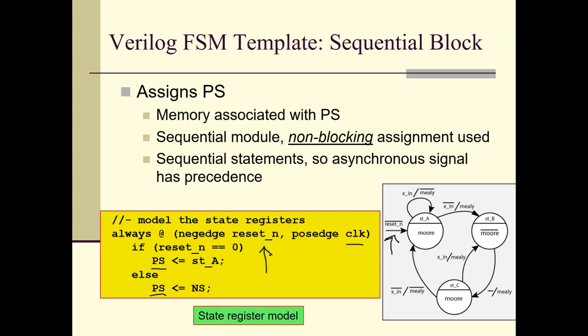This is done a little bit differently, and you can see it in the model there. The idea here is if the posedge kicked off this always block, that means that this line right here would be ignored, and this one would be evaluated. If the negedge set off the always block, this reset_n would be a 0, and this is what would be evaluated. Okay, so they work really nicely together on these things. The important thing is you understand that one's synchronous, the other one's asynchronous.